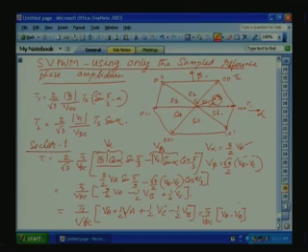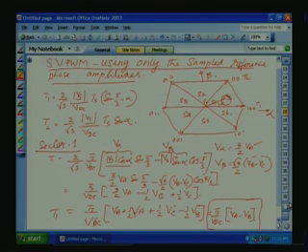What I want you to know in this case is that T1, originally written in terms of Vs and cos alpha, alpha with respect to the sampled reference phase amplitude in sector 1, we are now representing in terms of Va, Vb. So, if the 3 phase sampled reference phase amplitude is available, the sampling period is known, and the DC link voltage Vdc is known, T1 is known. This again we can represent in a simplified way. Let us go to the next page.